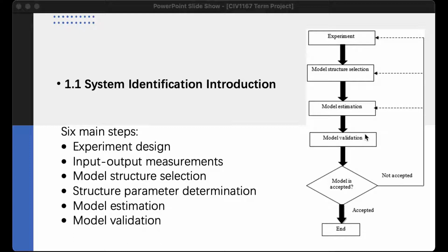The model-based control design process involves modeling the plant to be controlled, analyzing and synthesizing a controller for the plant, simulating the plant and the controller, and deploying the controller. Choosing a suitable model structure is a prerequisite before its estimation. The choice of model structure is based upon understanding of the system physics.